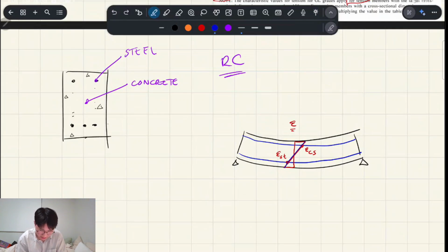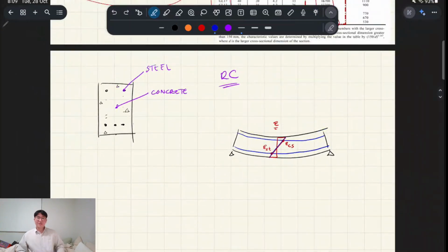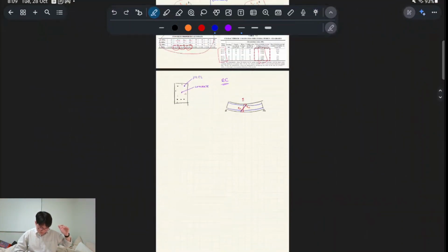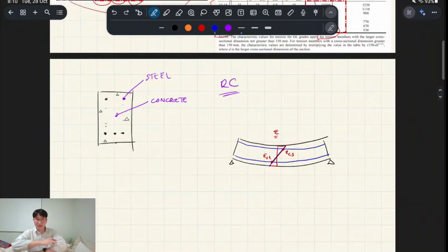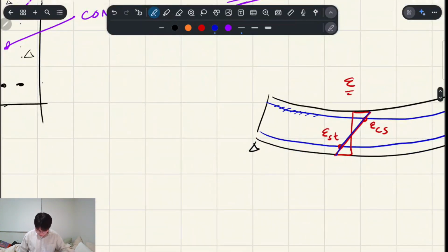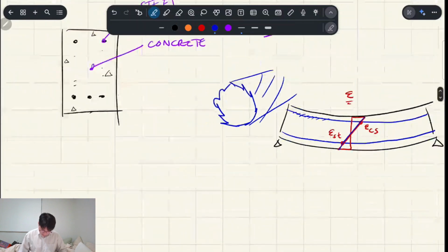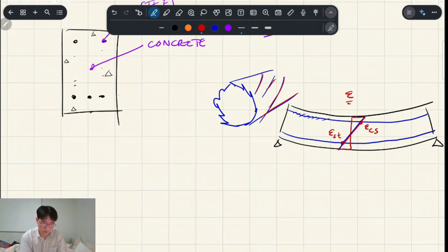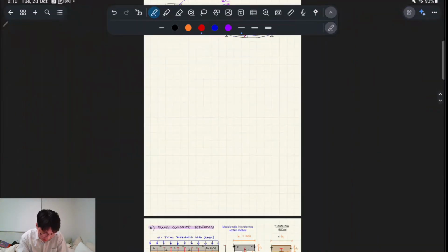So it's a straight line basically, and you can find these values. So basically what I'm trying to say is reinforced concrete is an example of a fully composite material, right? In all our design we assume the steel and concrete have a perfect bond to each other. One thing which contributes to this is the reinforcement is a deformed bar, which has better bond properties. So that grabs onto the concrete. That's a bit of a mechanical anchor as it bends.